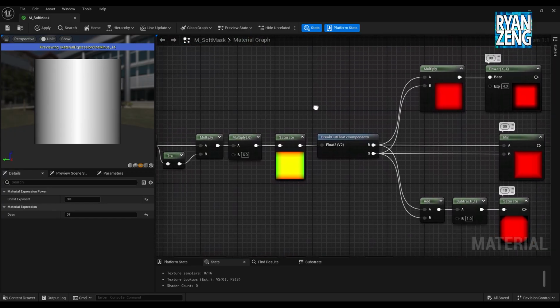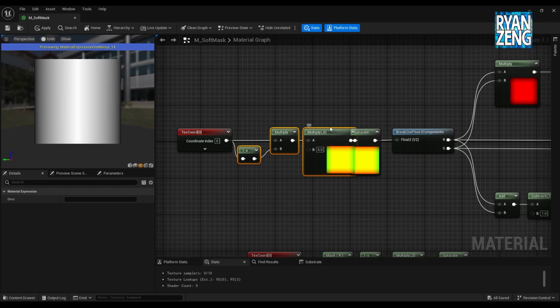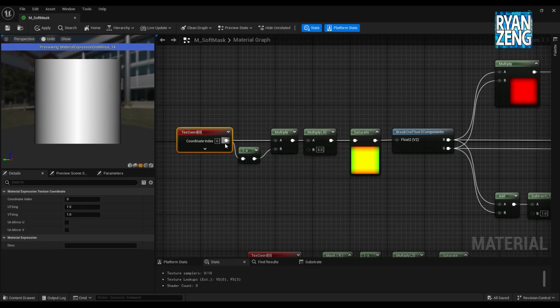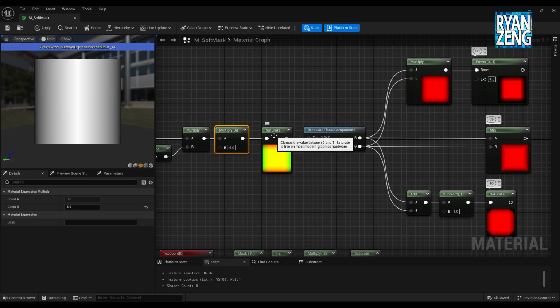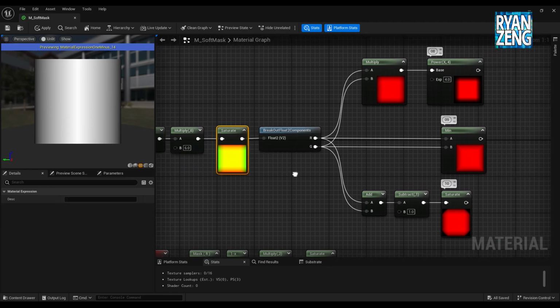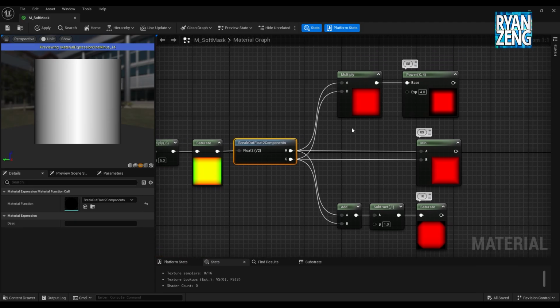And the next is a very general way of doing a mirror value. Here I multiply U and V with the 1 minus value and multiply by 6, and then ensure the value is just between 0 and 1, so I use saturate and break 2 nodes.